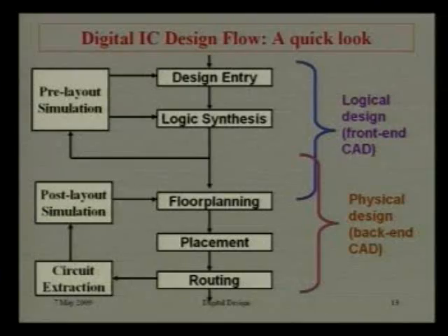See, your design entry or your Verilog code is nothing, it is only describing your circuits. That is why it is a hardware description language. Even when you run, you will be seeing that there is no error, that type of result is coming, nothing else. So just to verify, again you have to write some test bench separately. That means you have to give some input, and for that input what output is coming, that you have to forcefully embed manually.